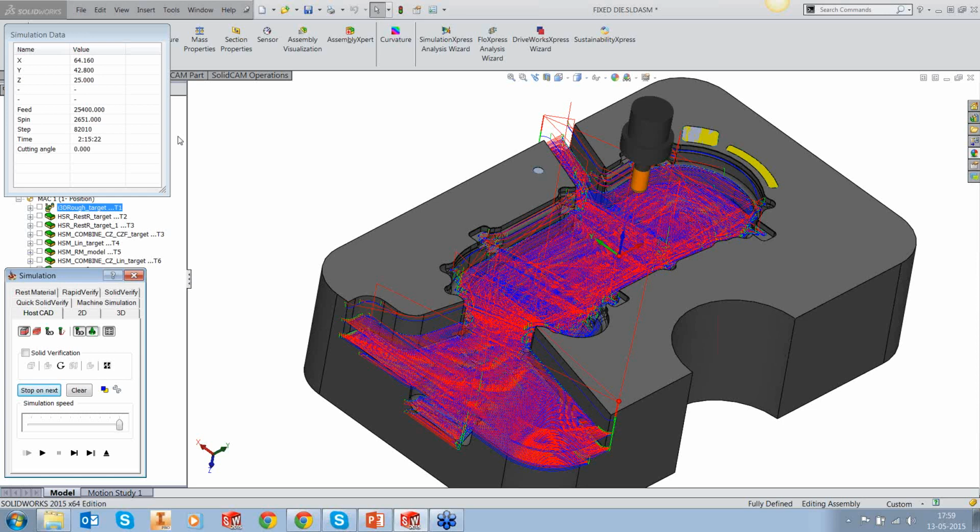Plus, remember that in iMachining, your tool life actually is pushed up. So even if you take the most conservative estimate of double the tool life, we are talking of 90 minutes and double of that, that's about 180 minutes. So we are falling within the ambit of the tool life parameter. And if your cooling, which in this case is going to be air, is perfect, then you could easily end up getting more than 180 minutes. If we are able to fall within the limit of the tool life, it's a great idea to go ahead and rough out this part with iMachining.